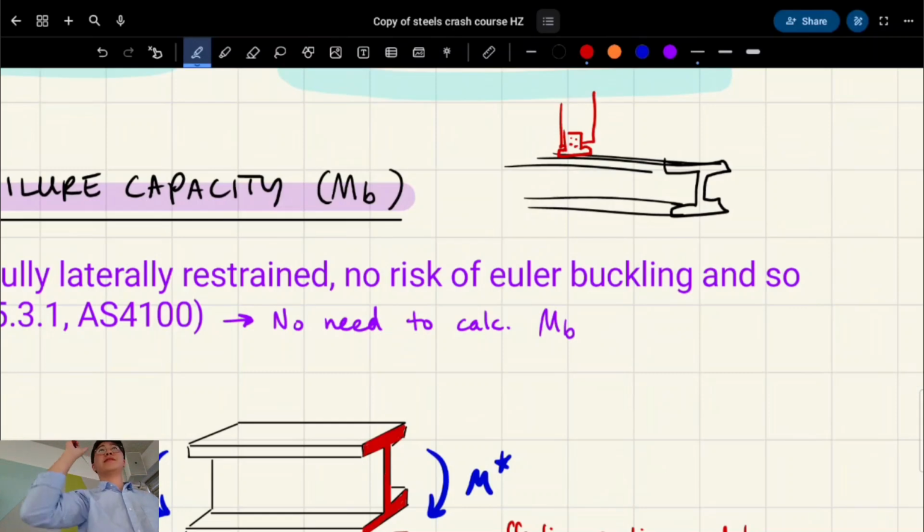That counts as a type of restraint, and there's a lot of details in the code about how things are restrained. Basically restraints act as little nodes where buckling can't happen, right? So instead of before, where buckling could have happened along the entire beam, now that fixes that member in place, if it's fully restrained, and buckling can only happen within that span. Does that kind of make sense?